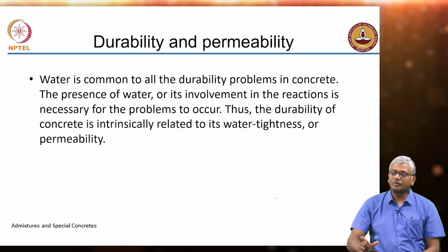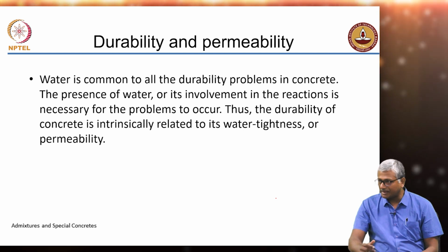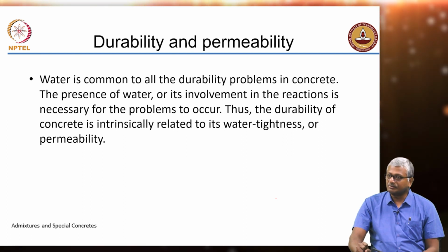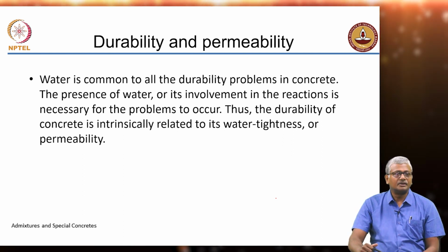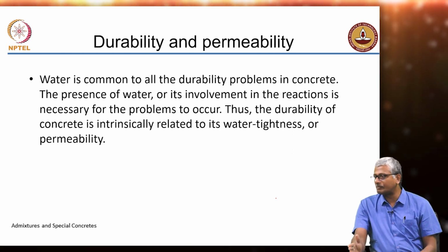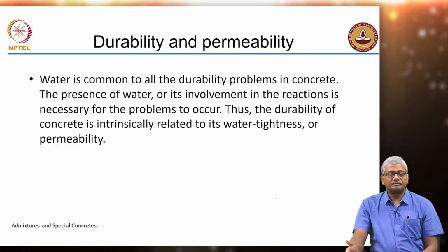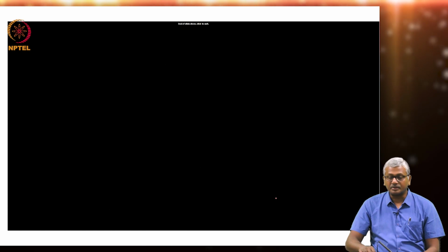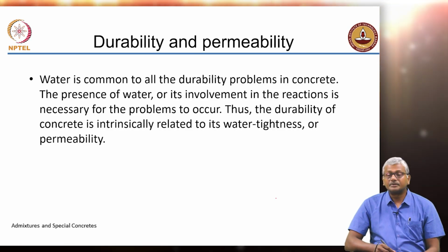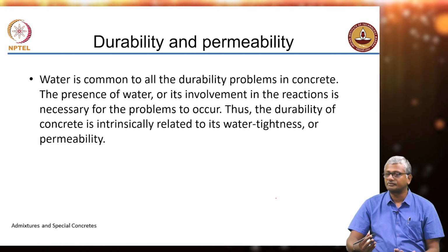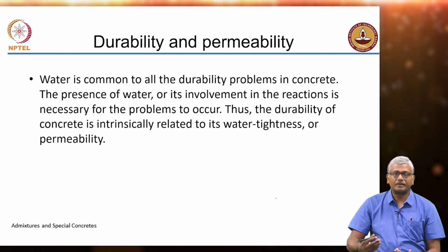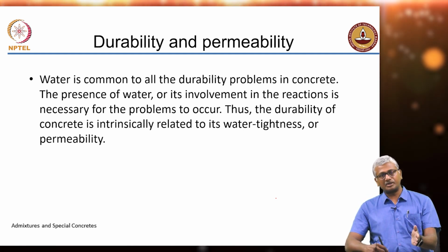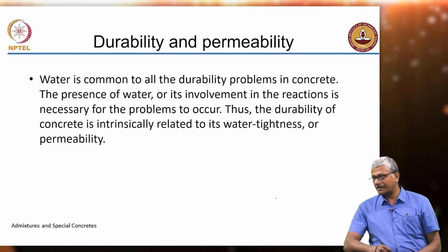So, because of this, if you keep concrete dry throughout its lifetime, you do not have a durability problem. If you keep concrete water resistant for a longer time, you do not really have many of the durability problems. Okay. So, very rarely you will have a problem created because of factors other than water. So, because of this we design concrete to be watertight or impermeable, sorry, yeah. So, durability is generally measured in terms of the permeability of the concrete. The more permeable the concrete, the less durable it is going to be. That has been the primary basis for defining the durability test methods that are typically carried out.